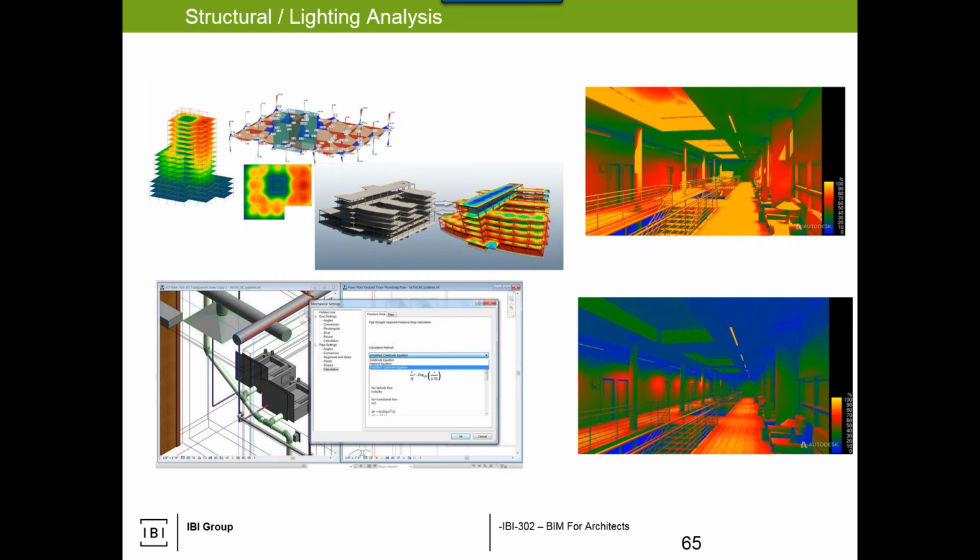Same with the lighting analysis. This one is very heavily dependent on the spaces itself. So the engineer can place lighting components and set the lights, but it's dependent on: are my walls hitting my ceiling? Do I have closed spaces? Am I having any light leakage throughout the building? Is glazing listed as glazing and all opaque listed accordingly? All of that will come into play and enrich or make the lighting analysis work. If it's not done right, the analysis will fail and therefore shouldn't be done.